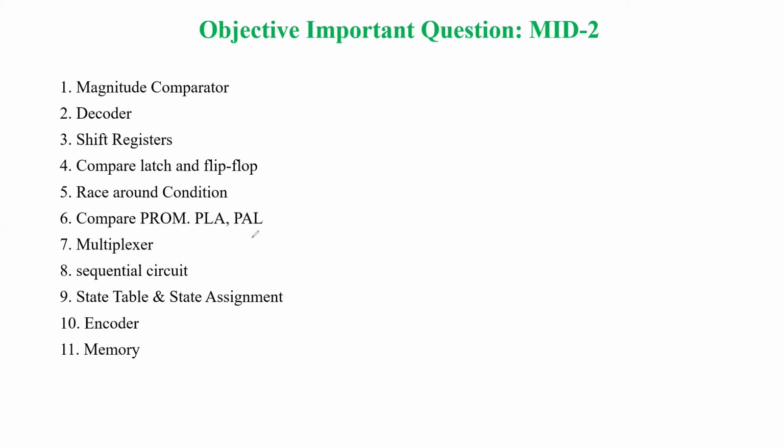Next we have compare the PROM, PLA and PAL. Or sometimes you have a separate question also: what is PROM, what is PAL, what is PLA. PROM, you know, is the programmable read only memory, but when we talk in terms of logic device, in case of PROM, when we design the PROM, it has an AND array that is fixed, and we have an OR array that is programmable. OR array is programmable.